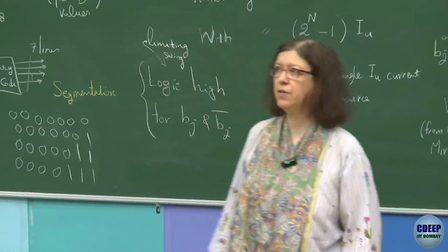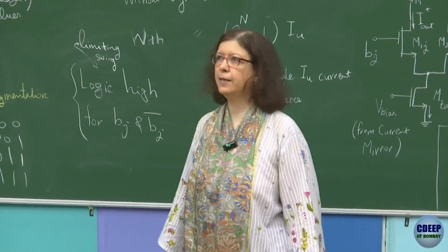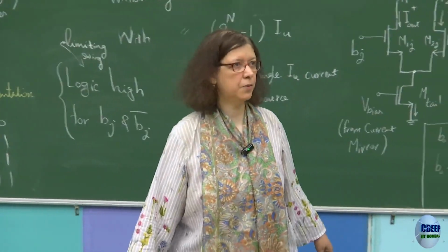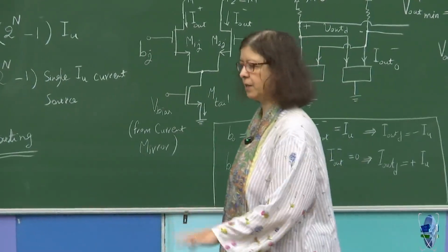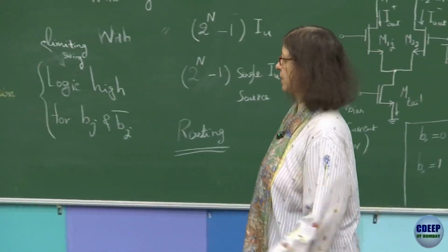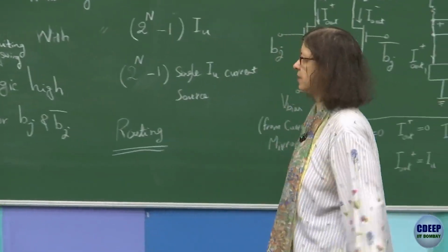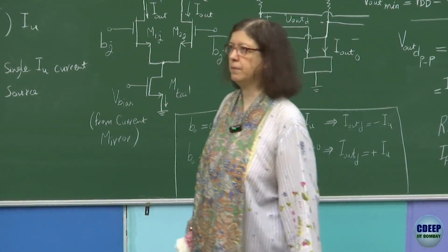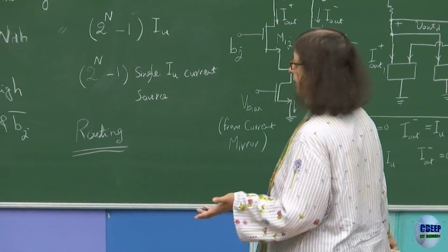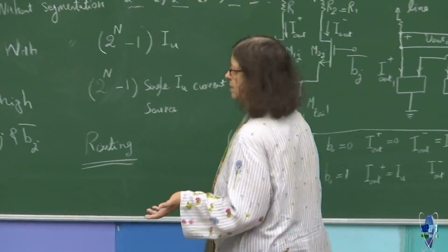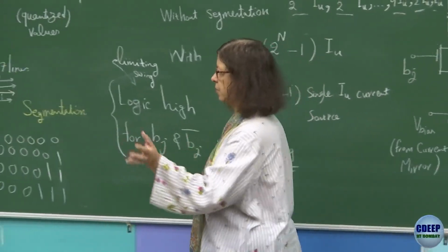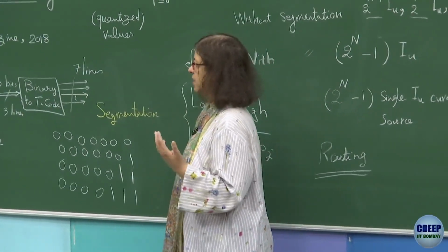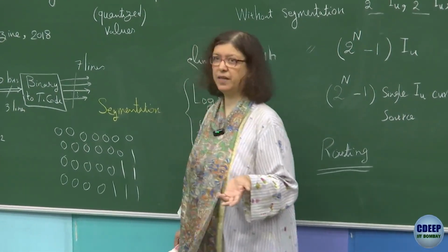Then we can have some discussion about the INL and DNL, at least with respect to operation. The design will come after that, because we need to look at non-idealities first, and then we'll talk about how to design this current steering DAC. For the design, we have tail currents, which are usually mirror transistors, and the sizing of the differential pair.